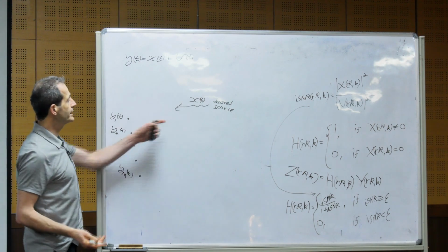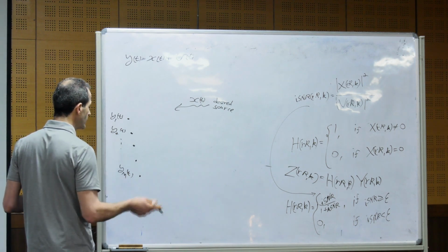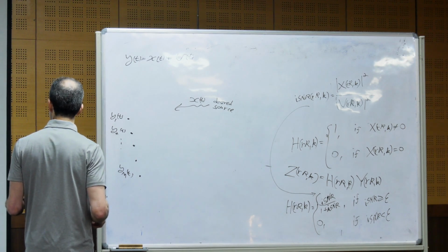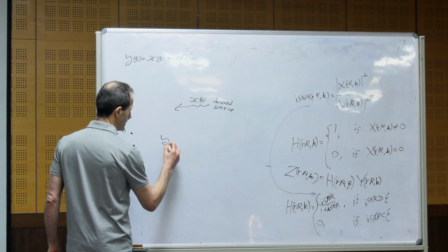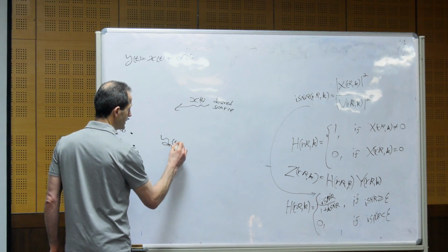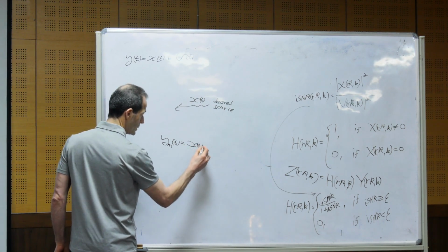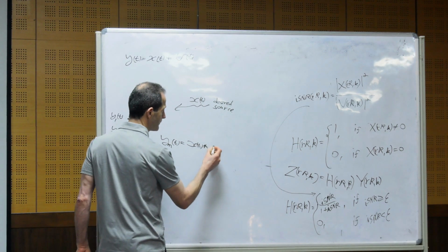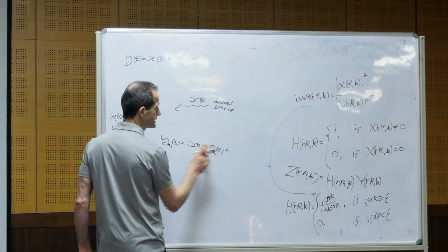So it's not only a delay, it can be an impulse response that takes into account all the reflections from all surfaces, and then we receive the desired source component in the first sensor, in the second sensor, and so on. So each sensor receives the source, including the effect of reflections, plus the noise in that sensor.